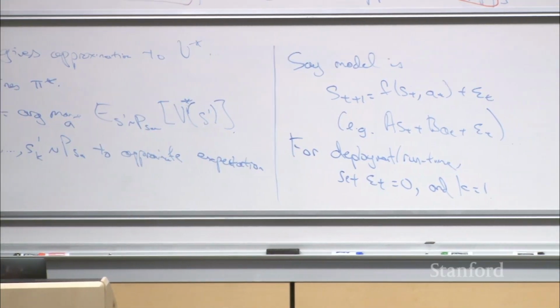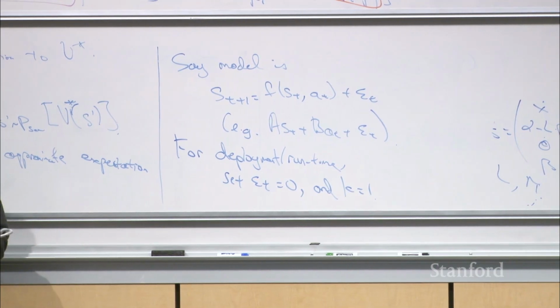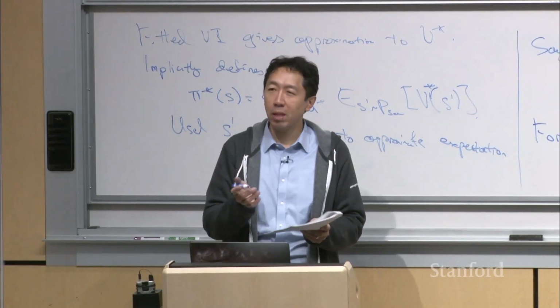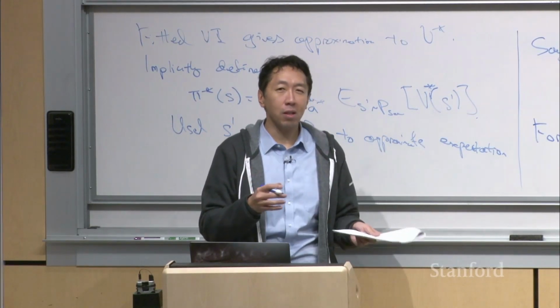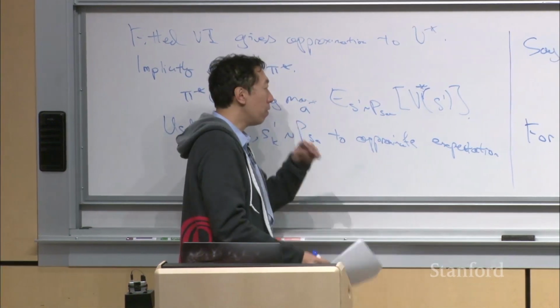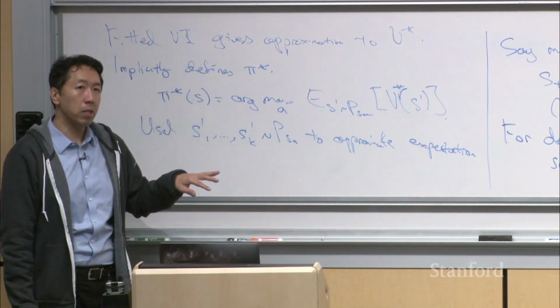And so, this is a reasonable way to make this policy run on a helicopter. During training, you do want to add noise to the simulator because it causes the policy you learn to be much more robust to little errors in the simulator. Your simulator is always going to be a little bit off. Maybe it didn't quite simulate wind gusts, or when you turn the helicopter, does it bank exactly the right amount? The simulator is always, in practice, a little bit off. So it's important to have noise in the simulator in model-based RL.